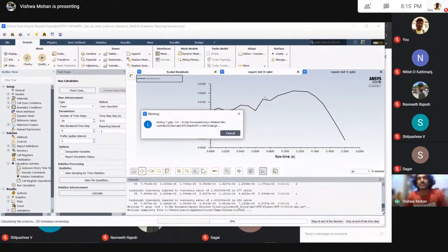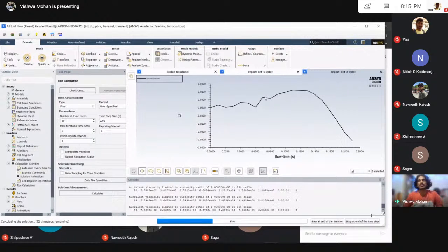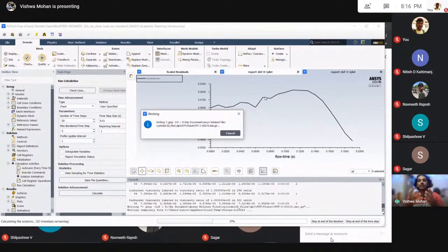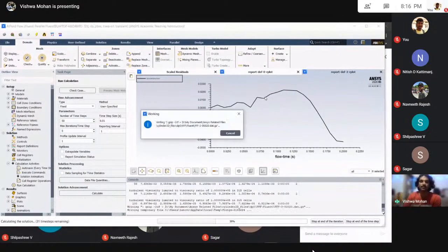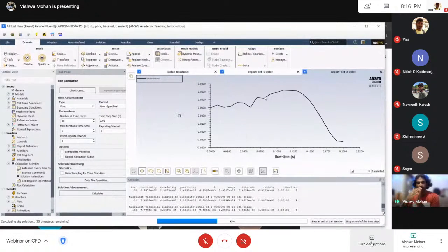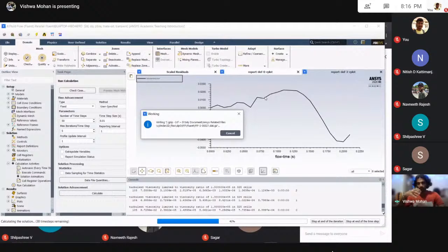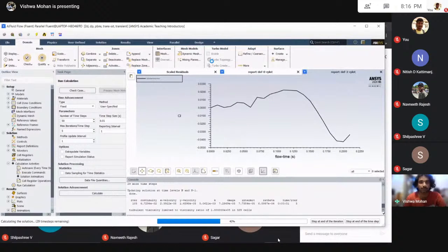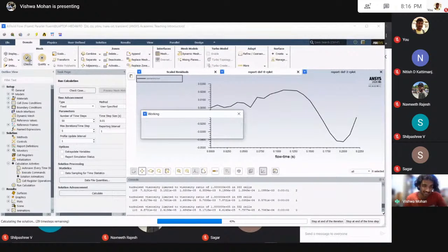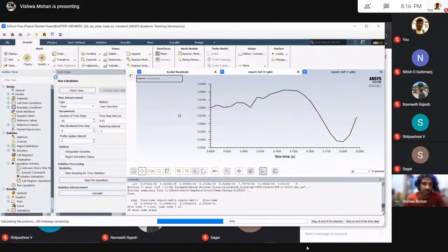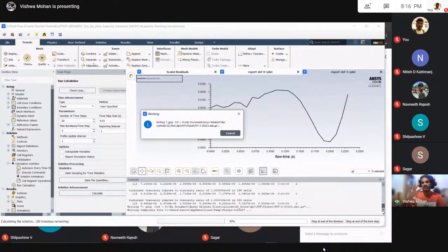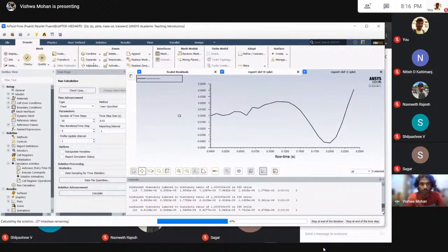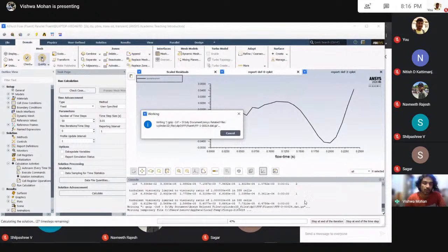Okay. So what mesh is, ideally what everyone wants in mesh is that you can find the flux flowing through the boundaries of that mesh. Every time the mesh is too skewed, has weird angles, or is a weird mesh, you can always hit on this or check the case over here. These two buttons tell you the improvements you need to make. So you go and check the quality as well.